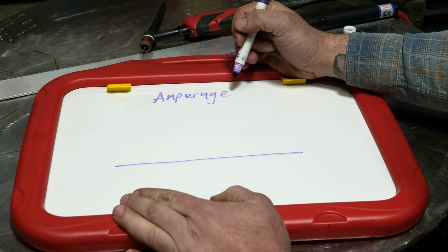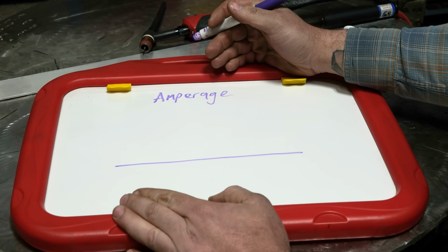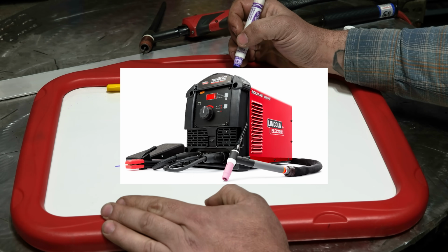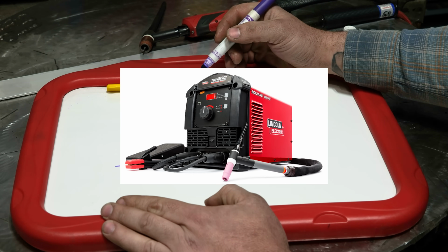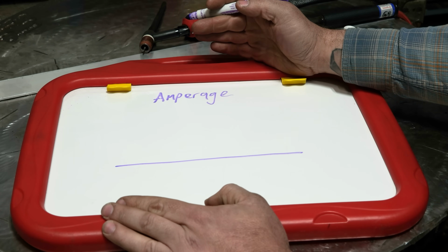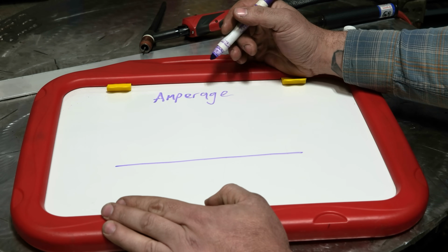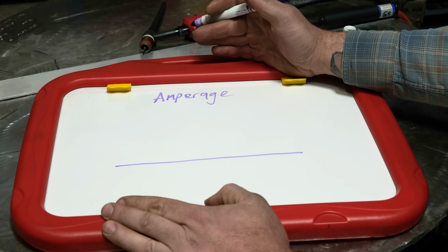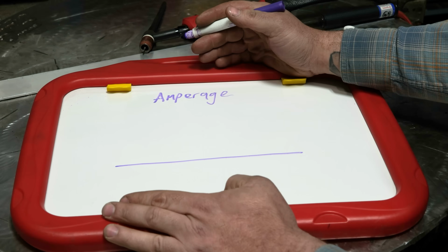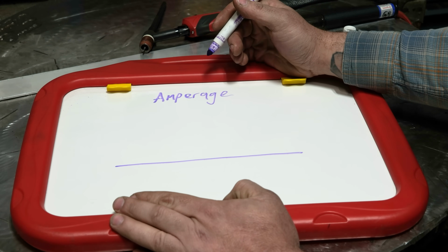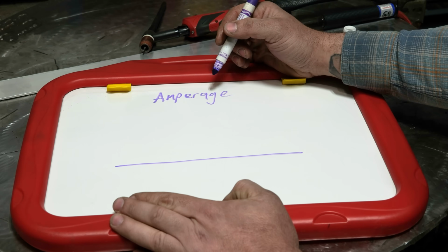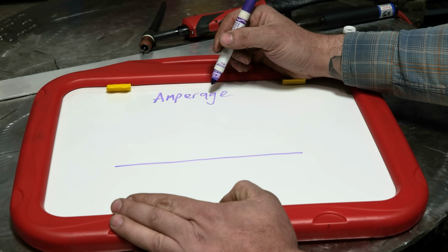Probably the biggest thing that I've learned since I've become very competent at aluminum welding with TIG is how understated amperage actually is. When I was looking for my first AC TIG welder, which happened to be a Lincoln TIG 200 many years ago when they first came out, the biggest selling point that everyone told me was features like adjustable AC balance and frequency and all of that, when the truth is, when it comes to welding aluminum, the number one most important setting is amperage. Aka, you need a big enough machine with enough amperage to do what you want to do.